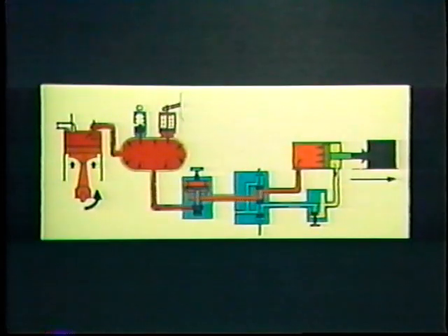Because it's so important, we should stress this point one more time. It is possible to control the speed of an actuator by restricting flow using a needle valve only if the total load on the cylinder remains constant. So if load resistance changes any time during the cycle, actuator speed will vary, even though the valve has been preset. Here is a basic pneumatic system that uses all of the components we've examined so far.